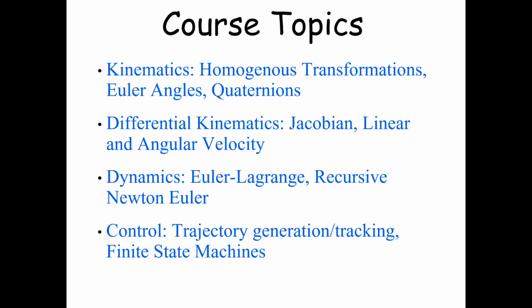The third part is you need to describe movement in the world space. Gravity is going to always conspire against you. So you need to be able to write equations. And that's actually another whole step. There's a lot of important things happening there because you need to make it fast enough that you can do these calculations on the fly. And once you have built all these three ingredients, then you go to control. You need to generate a trajectory and then you track it. So typically, if you want the arm to move from point A to point B, there's a trajectory which you generate, and then you go to track it. And dynamics or gravity works against you. There are also forces which come because of the velocity. You need to take those into account, and that would be the tracking problem.